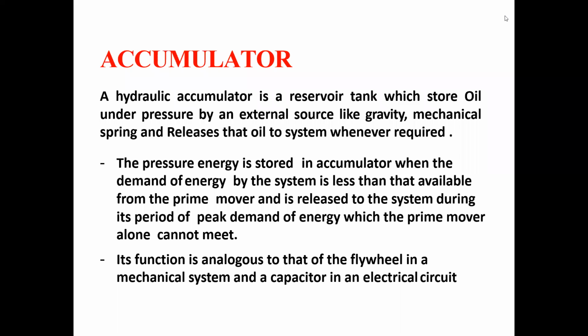When the pump is pumping oil which is not completely used, the accumulator stores this high energy, and when the pump is not capable of meeting the required high pressure oil, the accumulator supports the prime mover and supplies its high pressure oil.